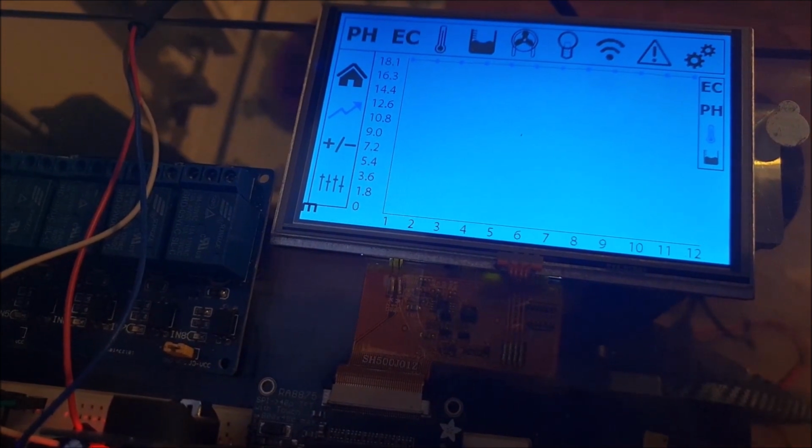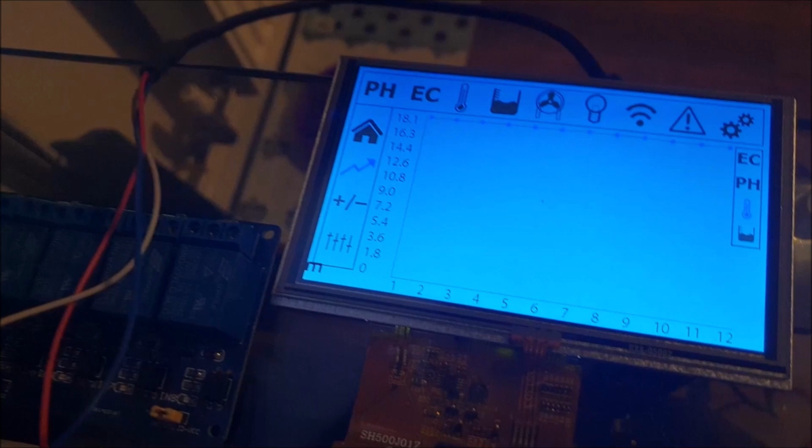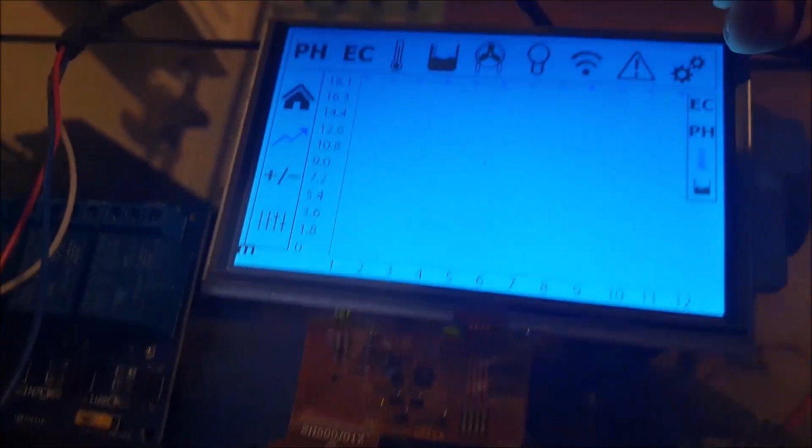It's got 4 meg of memory, your standard ESP essentially. So the data is sent over serial to the ESP, and the ESP then sends it to the server, or essentially it sends it to a PHP handling script. The PHP handling script puts it in the database. I think I've blabbed on enough about that.